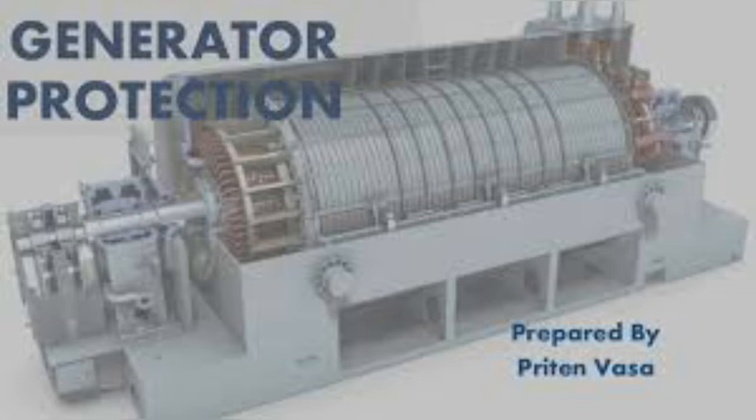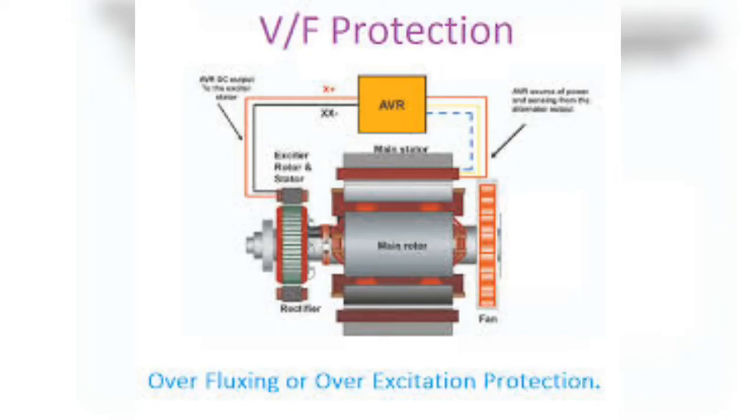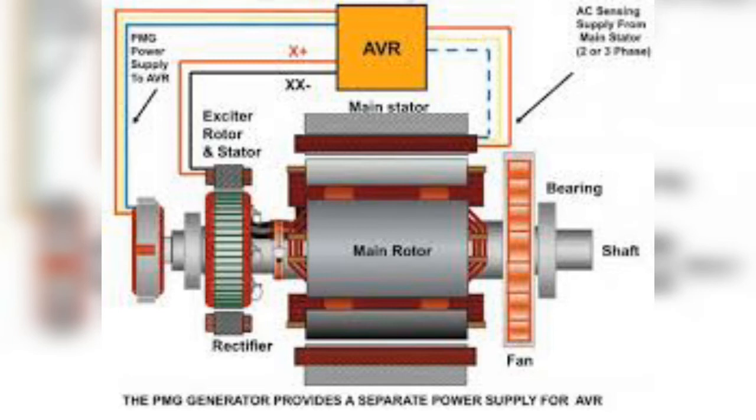This protection operates within a microsecond or a millisecond and the generator will be stopped, whether the fault occurs phase to phase or as an earth fault to the phase. It also protects the winding from major damage.